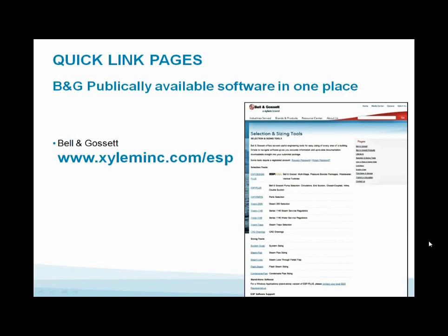For you old guys like me, and I'm an old guy with gray hair, I do like that manual system sizer. The limitation of the manual system sizer is it's only good through 12-inch pipe. Another limitation has nothing to do with NPSH on it. So I would strongly recommend you get the Windows-based versions and spend some time with this. You cannot find a more important tool for every engineer, every contractor, every young person coming into this industry to learn. You need this desperately.